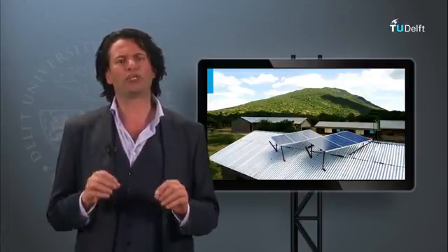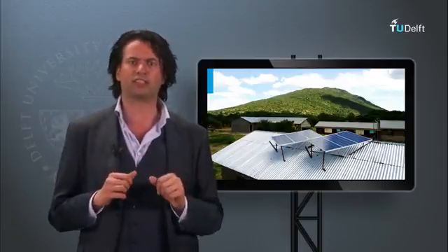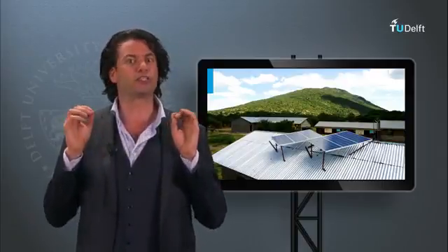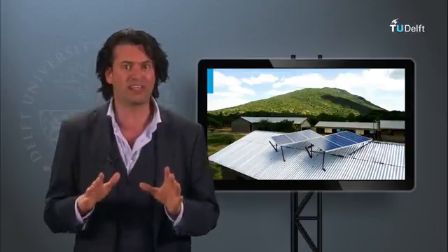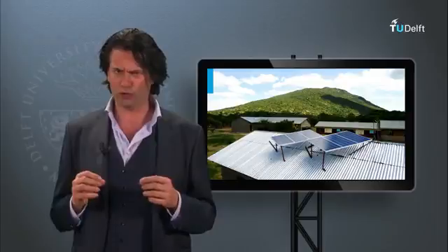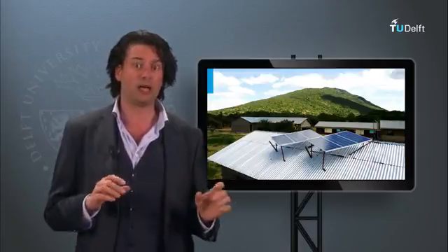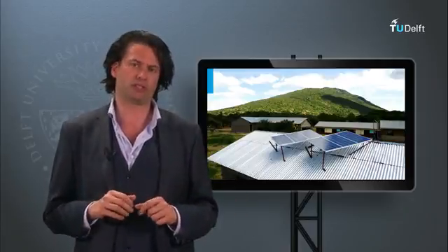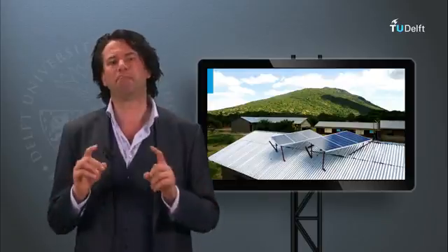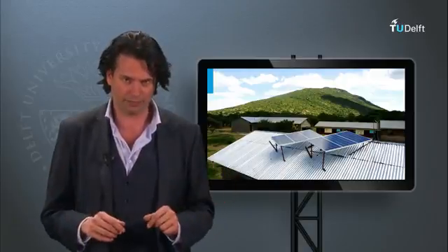For places with severe disparity between the summer and winter irradiances, the number of autonomous days would increase for winter and the system cost would consequently rise. Also, the component margins considered for various parameters could differ from place to place based on the system requirements. Nonetheless, this method is good enough to get a basic estimate of the standalone PV system sizing.